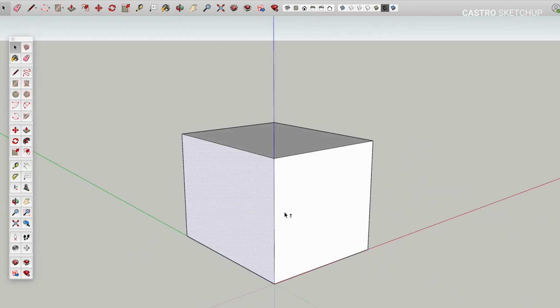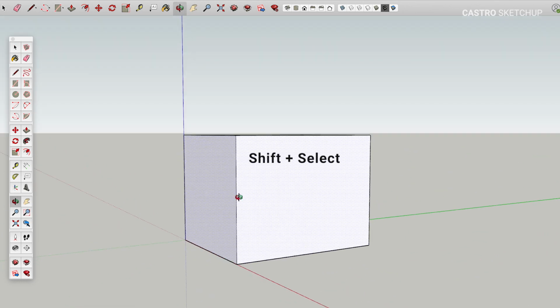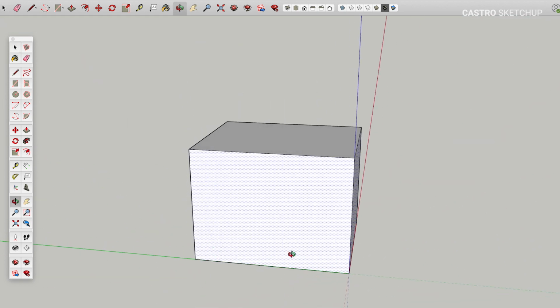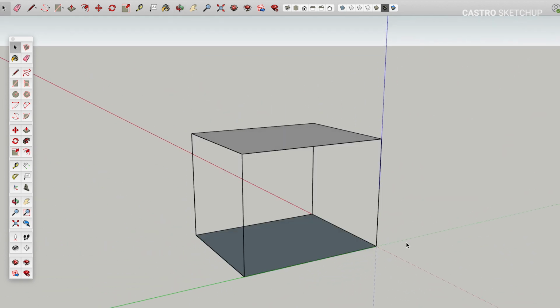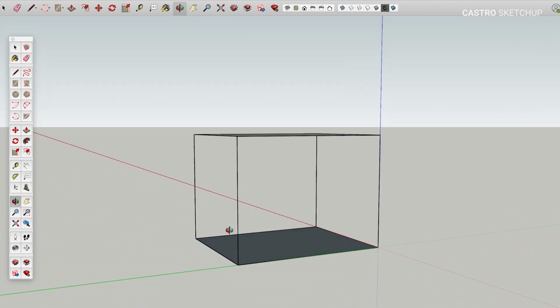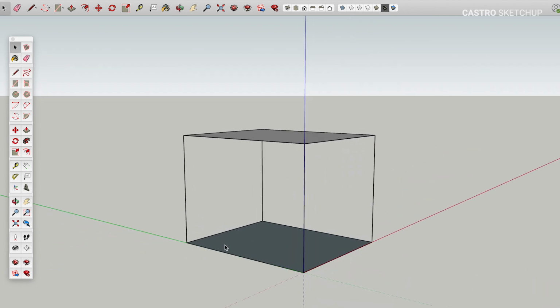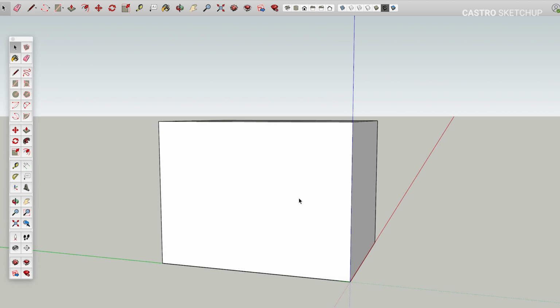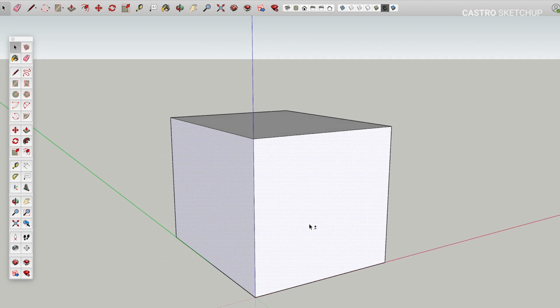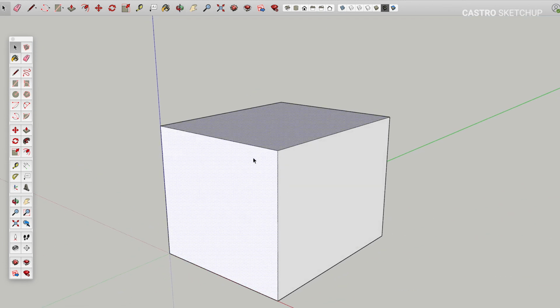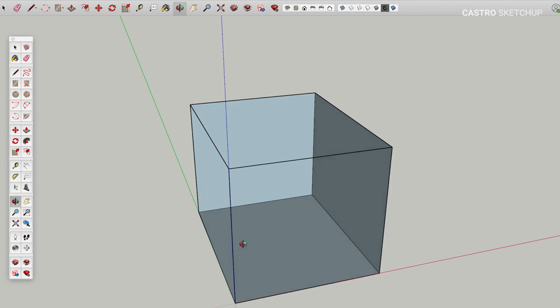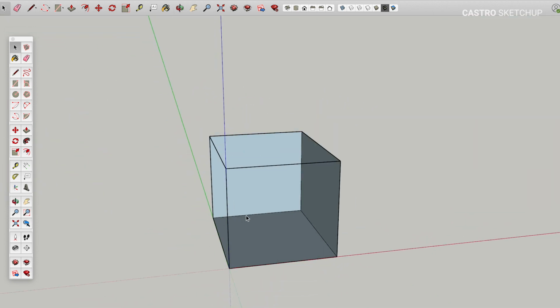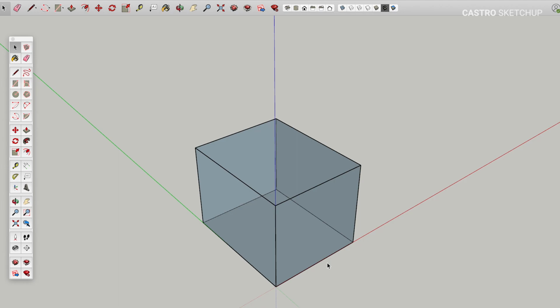Right now, SketchUp is allowing us to select multiple things. When I hit delete, you can select multiple things to delete at once or manipulate at once, depending on the command you're exploring. Again, I select, then Shift to select an additional thing, Shift to select something else, and once I hit delete, all of those are deleted at once.